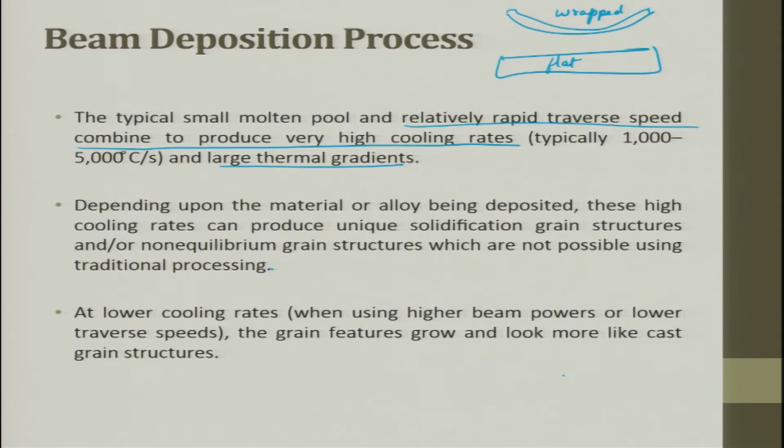So, we know that by extracting the heat, you can try to dictate the grain structure. If you extract it in different directions, or if you can control the extraction of heat, you are controlling the grain structure. You can create columnar grains, or you can try to create uniaxial or equiaxial grains, and this dictates the final property.